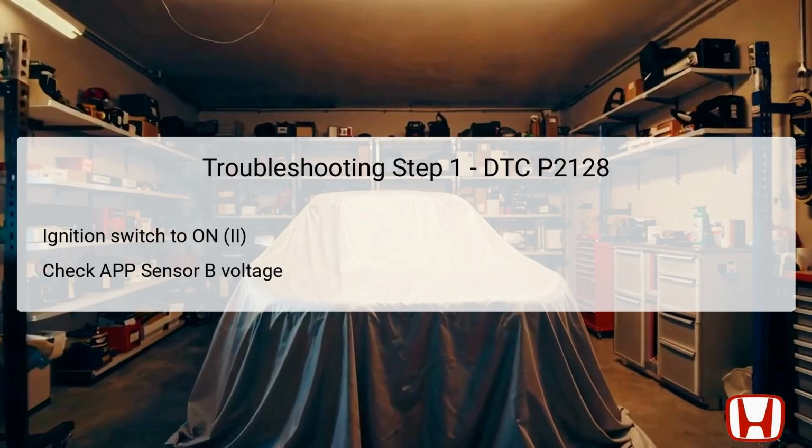The first troubleshooting step involves turning the ignition switch to the on position, also known as position 2. This will power the vehicle's electrical systems without starting the engine. Subsequently, using the Honda Diagnostics System, HDS, check the voltage of APP sensor B in the data list. It is crucial to determine if the voltage is about 4.9 volts or more.